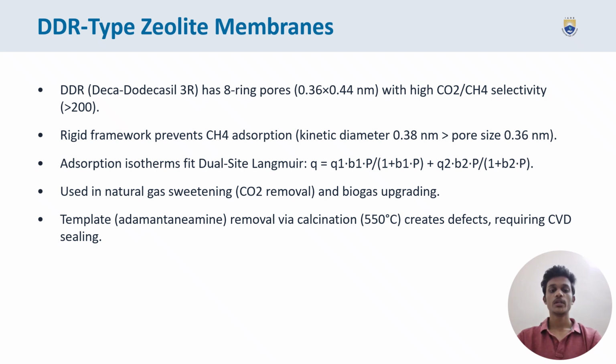DDR type zeolite membranes. DDR has 8 ring pores with high selectivity. Rigid framework prevents CH4 adsorption. Adsorption isotherms fit dual site Langmuir. Used in natural gas sweetening and biogas upgrading.